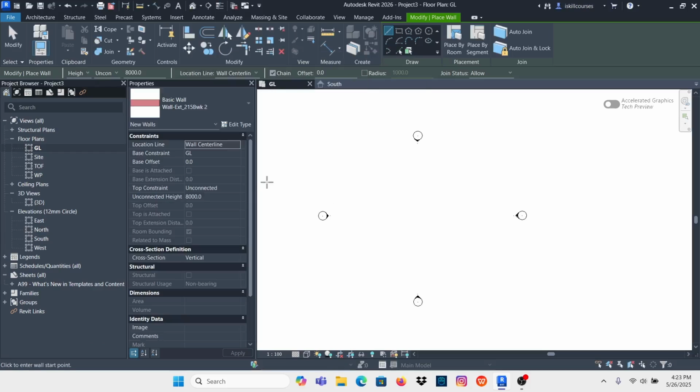Now to add the walls, make sure that you watch out for the toolbar here. Also, you watch out for these options here. I'm in the wall command. Make sure that you pick height, because I'll just cancel there. I'm at ground level, and now I want my wall to go up to wall plate. Okay, then the other options, leave it the way it is.